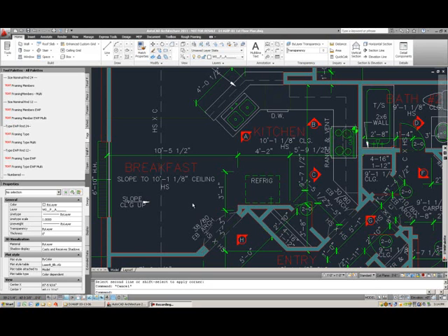And if you're dealing with that, you only have a certain number of layers, because you only want about 8 or 10 colors in your plan, so you know how that's coming out. It's very simple. With BIM modeling, you're not so concerned with layers, because how an object prints is determined by plot styles. That's determined by the style or what layer it's on, regardless of color.